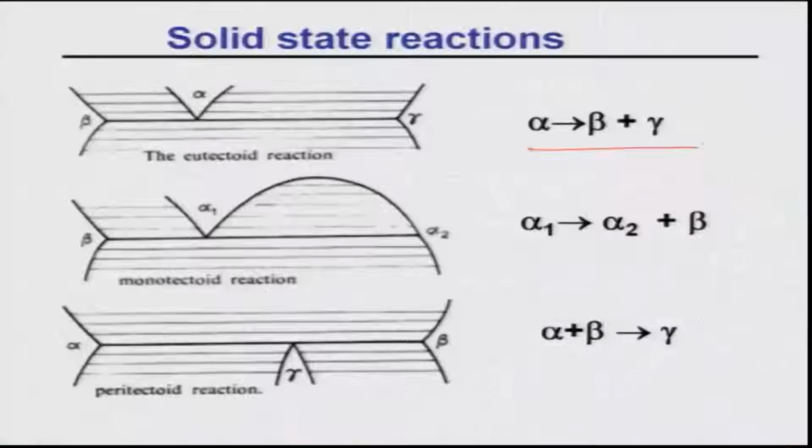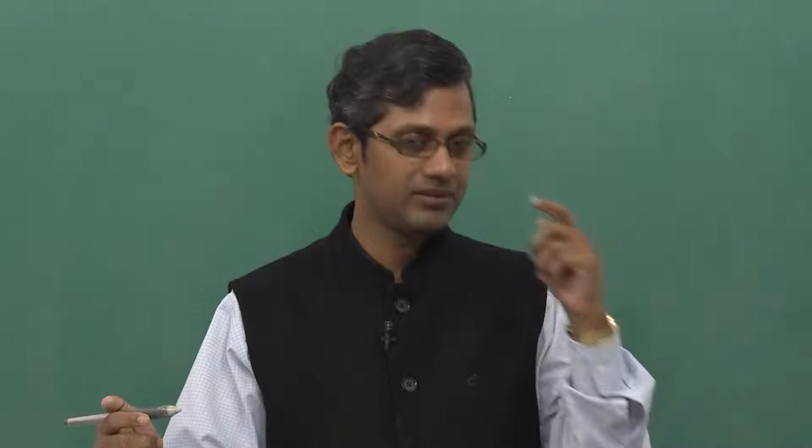Basically for the steel the most important reaction is this pearlite formation reaction, and that is a Eutectoid reaction. So, I know that that reaction is given by gamma going to alpha plus Fe3C. On the left side I am just showing you the appearance of the phase diagrams if such a reaction is present. This is again taken from Professor Alan Prince's book, you can look at it carefully. We had a lot of discussion for maybe 8-10 lectures about that, and that brought about steels and the cast iron.